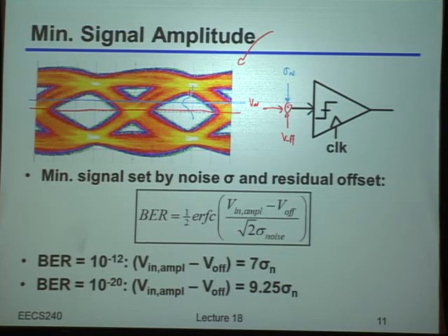If we draw things this way, and we want to know how often we're making an error, then as we said before, what we really need to know is how often that noise I've drawn is going to be larger than the distance between my threshold and the smallest input signal that I'm actually receiving. On this picture, what that translates into is the area under that PDF curve that goes beyond that minimum input signal.